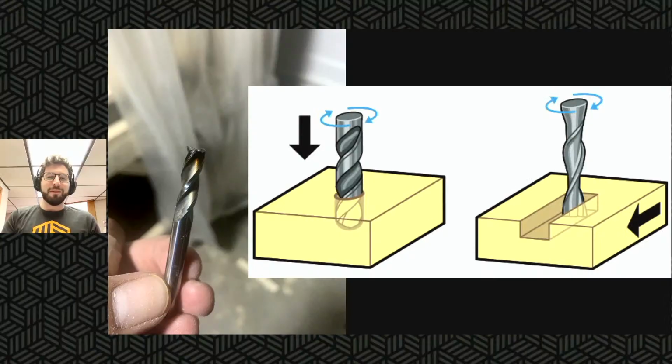So the next big improvement to Easel Toolpath involves plunge moves. This is something we've heard from many customers about. In fact, I just read a comment in the chat on YouTube about it. Plunge moves happen when a bit plunges vertically into the material. And it's usually not great to plunge vertically with an end mill. On our CNC routers, we use spiral bits, either up spiral or down spiral end mills. They don't work as well drilling holes as drill bits do.